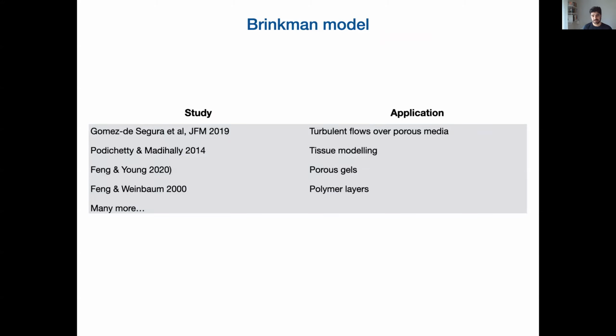So clearly it is being used, and it is a useful empirical, semi-empirical model, I would say. However, the issue remains of determining the appropriate Brinkman viscosity. And previous mathematical work in particular has shown that, in certain limits, the Brinkman viscosity should equal the molecular fluid viscosity. So the ratio between the two should be 1.